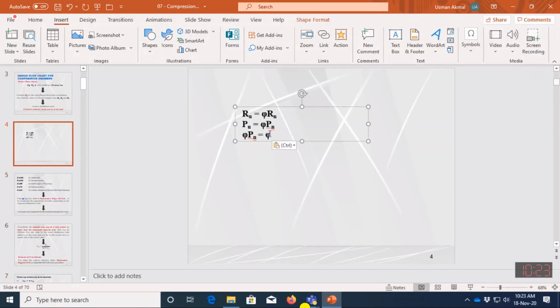So load is equal to stress multiplied by area, that may be the gross area. Here in our steel structure we represent the stress by F. So the F value is the stress value, the strength limit. So load divided by area is equal to stress, or capacity will be equal to the failure stress multiplied by the gross area.